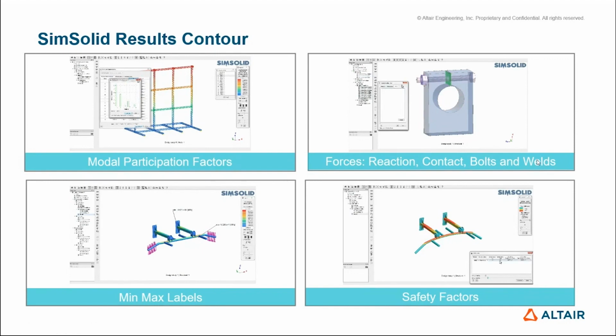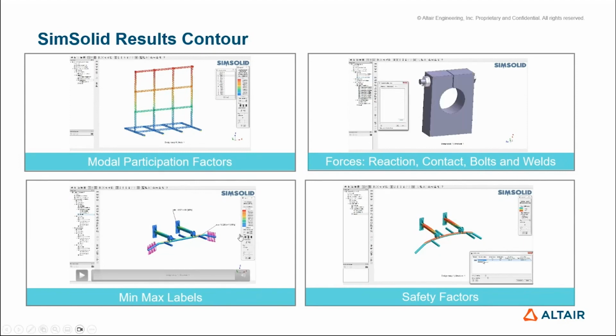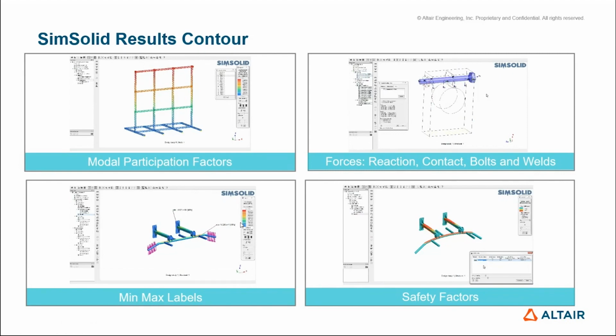So very important for welds, you can extract your shear forces, normal forces, bending forces, and bending stresses from the welds. Very important for weld design. Of course, min and max labels, where's your maximum result. Safety factors, important when conducting linear analysis.